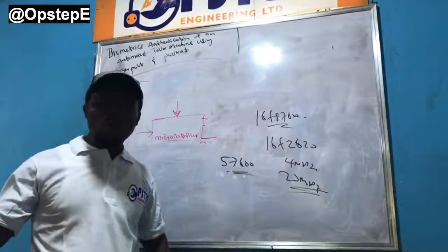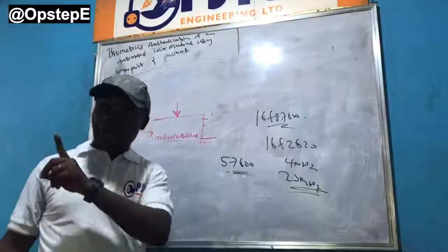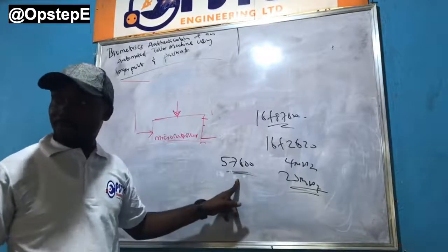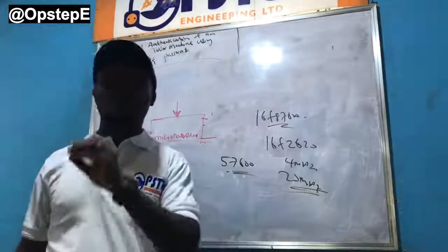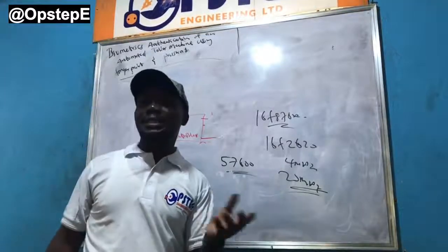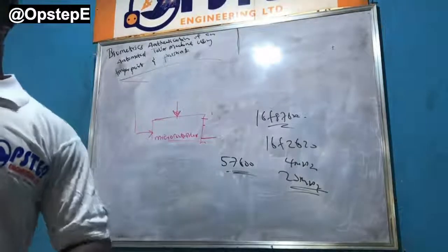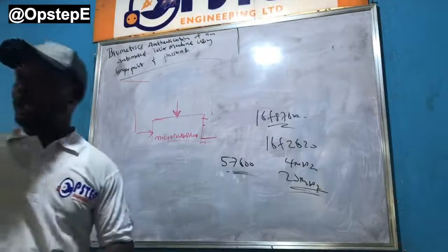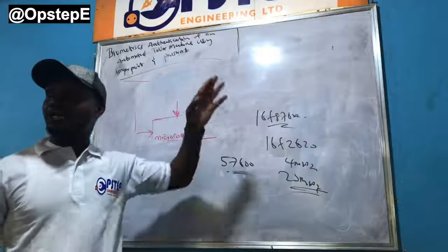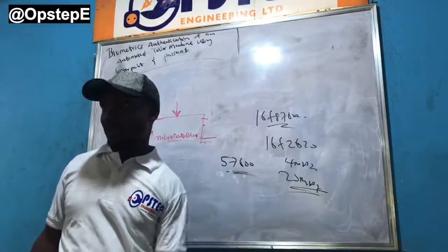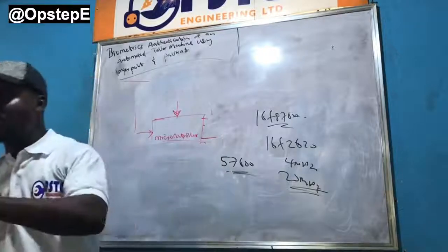Do you get it? So we can say that the choice of this microcontroller, firstly or partly, is the choice of baud rate that we're working with. For other UART modules, what we usually do is that we connect it to the laptop, and then it has a way where we can actually reduce the baud rate. Are you getting it? So sometimes some of them require this baud rate, we sometimes have to drop it to maybe 9600, which any 4 megahertz crystal on the microcontroller, not running at high speed, will do.